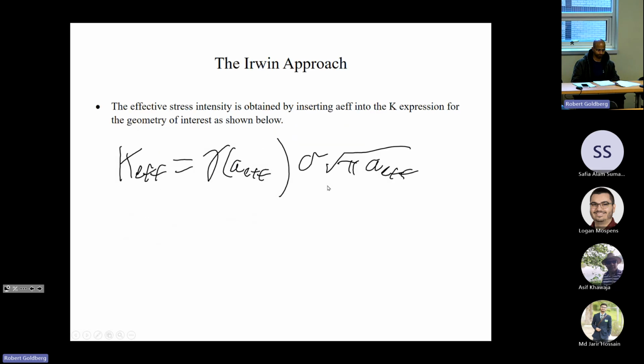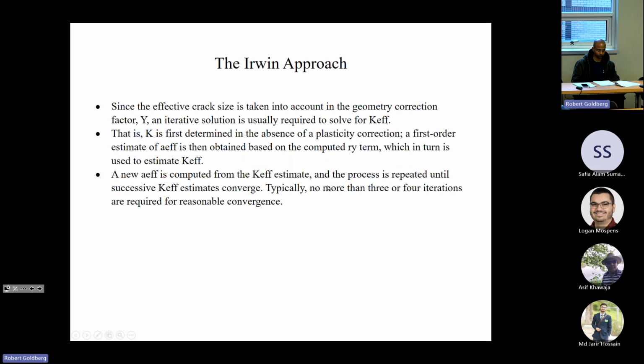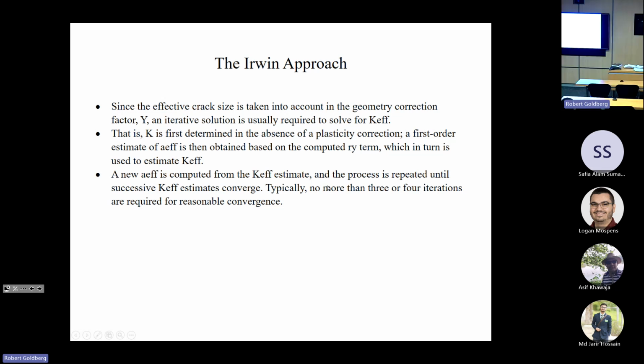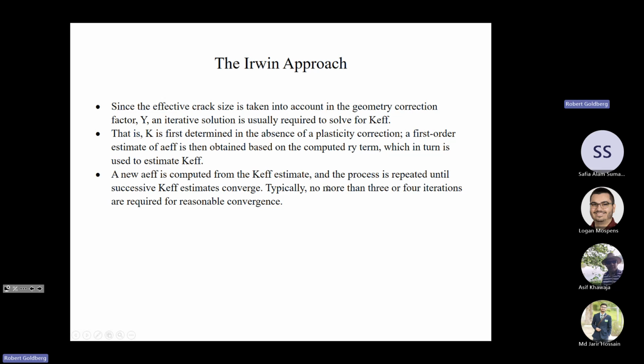Then you can compute your new stress intensity factor based on this expression. You repeat the process until everything converges. Typically, only 3 to 4 iterations are required for reasonable convergence.